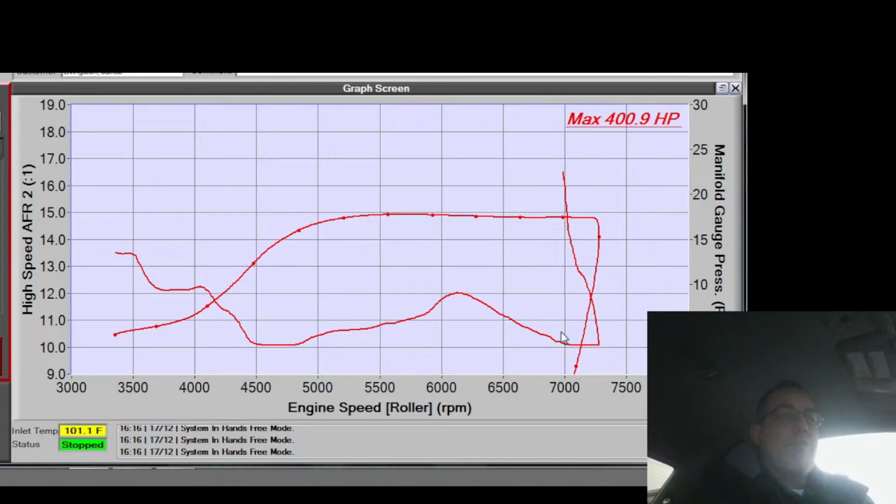And that's why if you fire a race car up that has race car plugs in it, usually like heat range 5 or something, and you move it like 2 or 3 times, your plugs are fouled, you're screwed. If you don't let it warm up, you don't put some load on it, the plugs won't get hot enough to clean, and they'll get fouled, and you won't be able to recover them, and you've got to change the plugs again. So self-cleaning is number one.